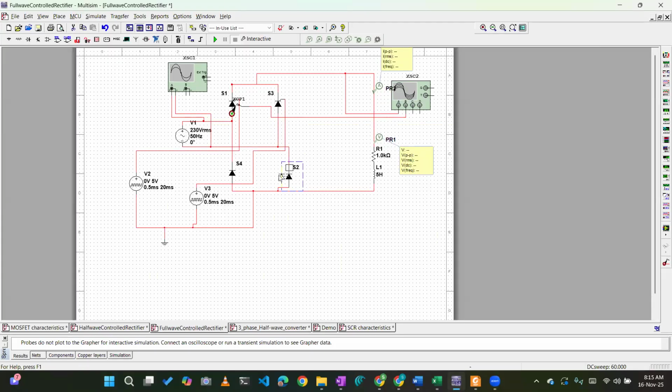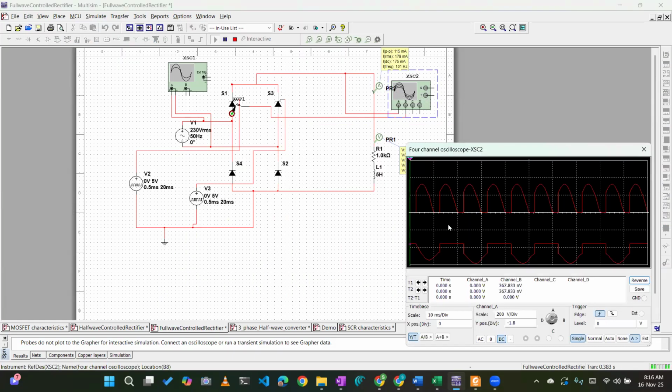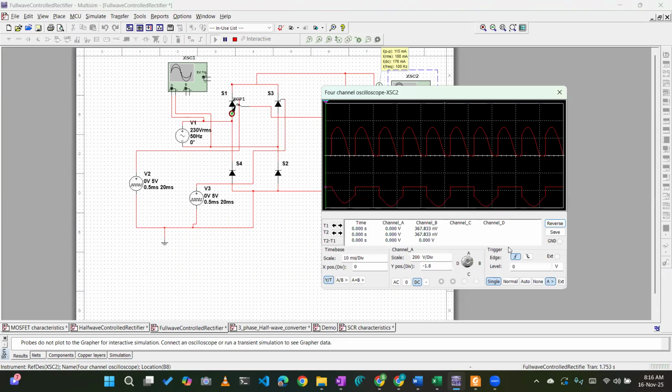Now you see this is nothing but a full bridge half control rectifier with two diodes in a symmetrical configuration. This is the circuit. Now if you see the output waveform, even with inductance, you will see the freewheeling effect. Output voltage does not have negative values. That is what theory says, na? About a single phase full bridge half control rectifier. And what is the conduction angle?